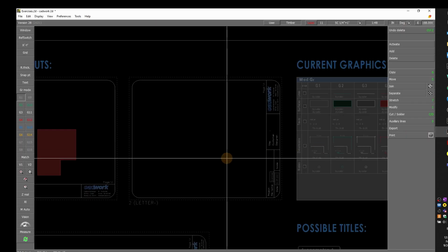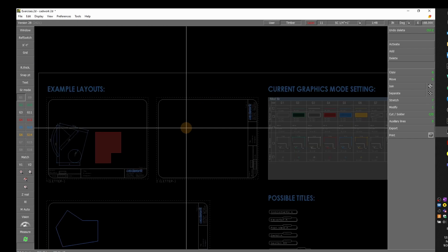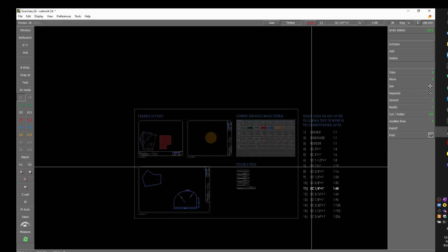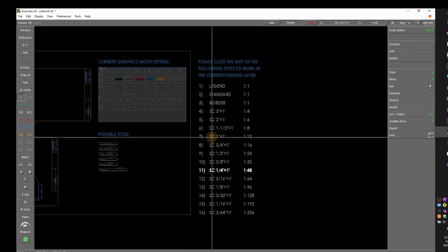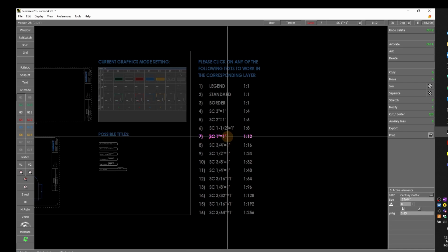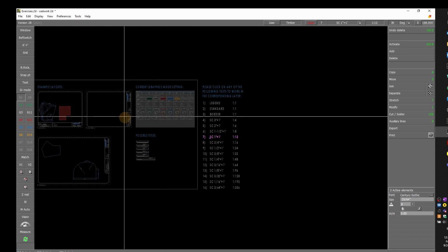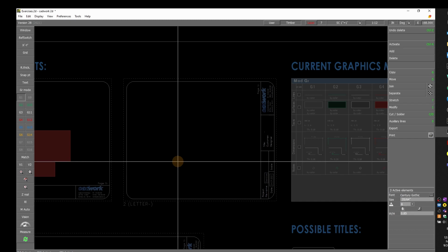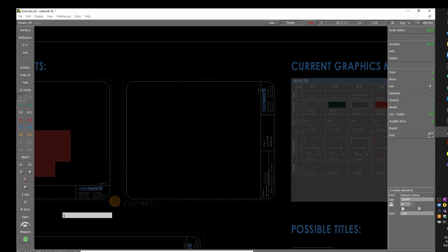Then you switch to Cadwork 2D, and before you paste, we said we want to make sure we fit that in here at scale 1 inch equals a foot. So you select the layer, and then you press 3 to paste the clipboard. So here, as soon as you press 3, it's asking you for the clipboard number.